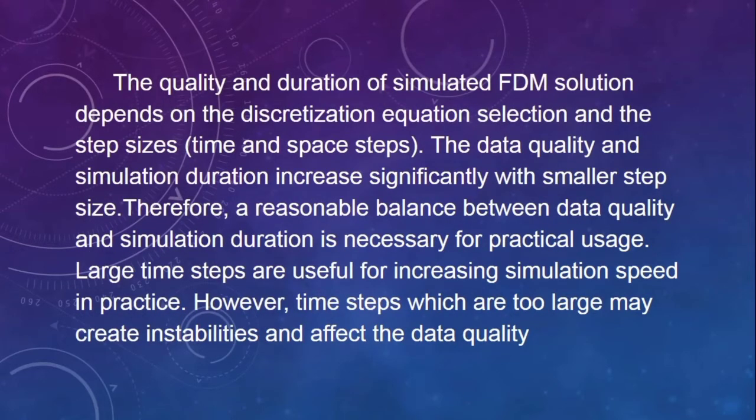The quality and duration of a simulated FDM solution depends on the discretization equation, selection, and step sizes, or time and space steps. The data quality and simulation duration increase significantly with smaller step size.